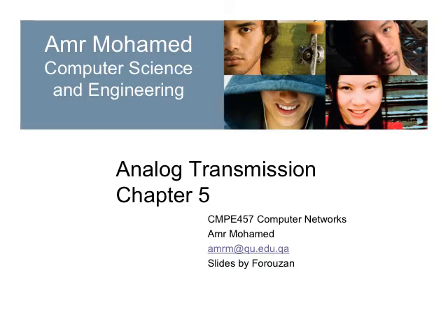Okay? So if your channel is a band pass channel, an example of this, as we said before, is what? Wireless, bravo. What else? ADSL. Okay? So sending digital data over ADSL, that's a band pass, because if I send it in the zero frequency component, guess what will happen? It will interfere with what? With our voice. Because we're trying to send the data and the voice over the same line, so I have to have separation. Right? So we talked about that before.